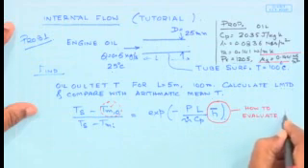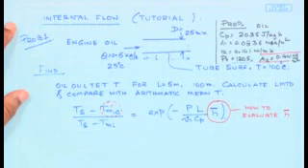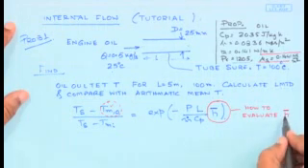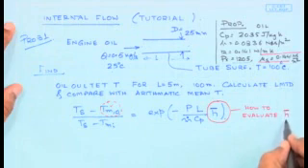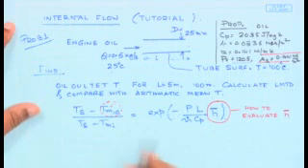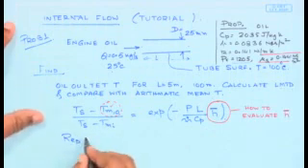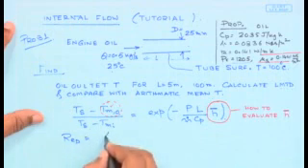So, that's all there is to this problem, how we are going to find the value of H bar. Now, whenever we try to find the value of H bar, we need to know what is the flow pattern. Is this a laminar flow or is it going to be a turbulent flow? That's the first thing that one has to evaluate, and therefore, in order to do that, I have to find out what's the value of the Reynolds number, which is 4 m dot by pi d mu.